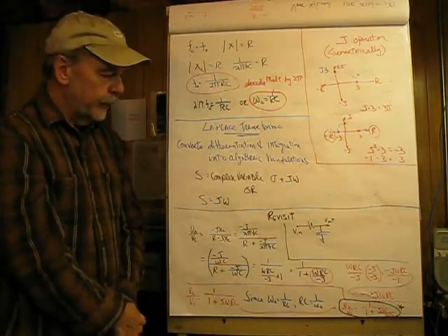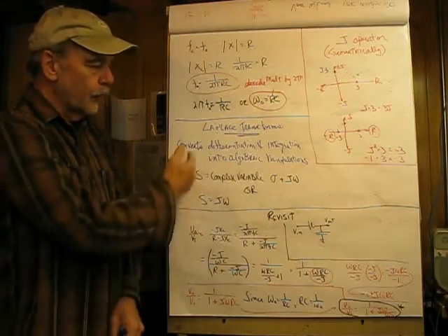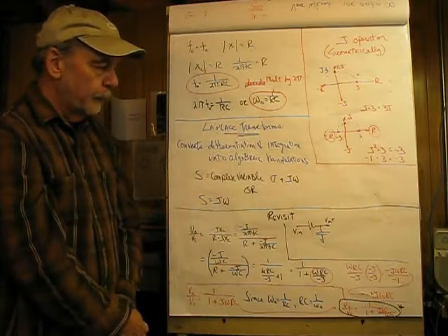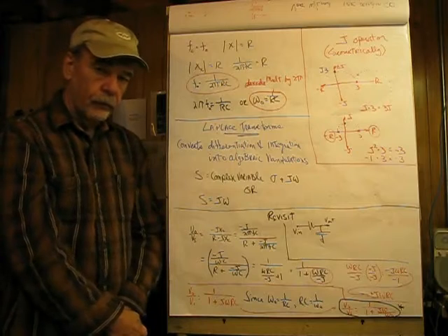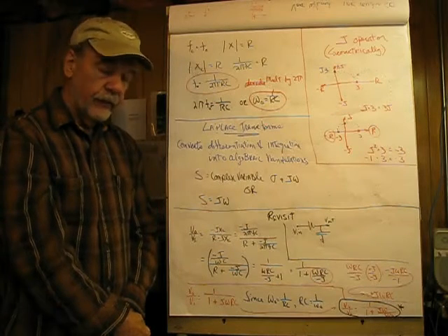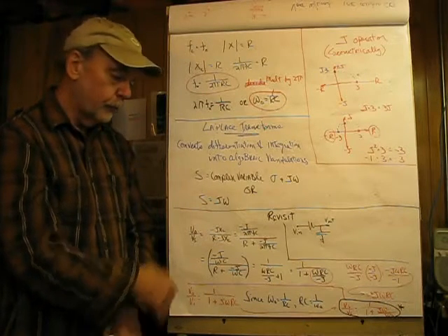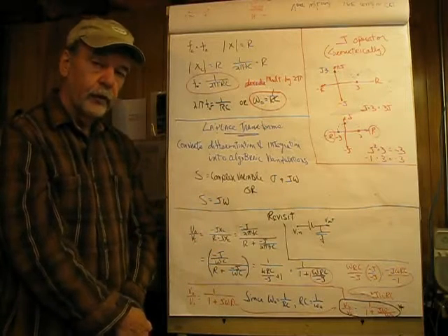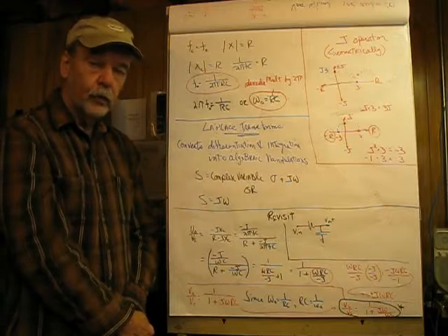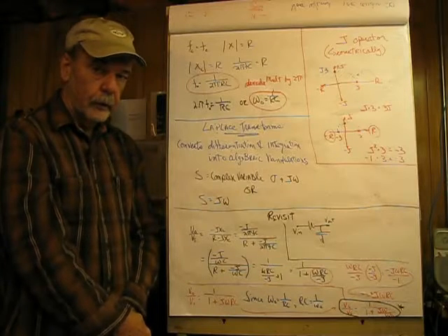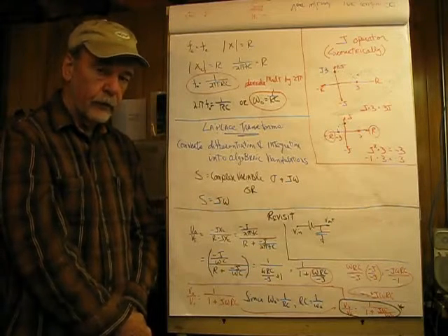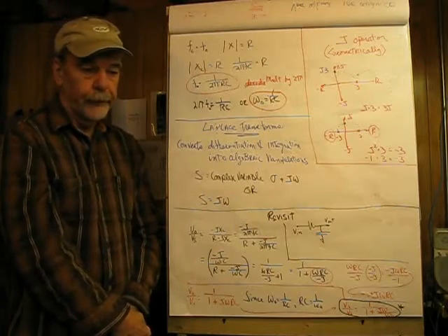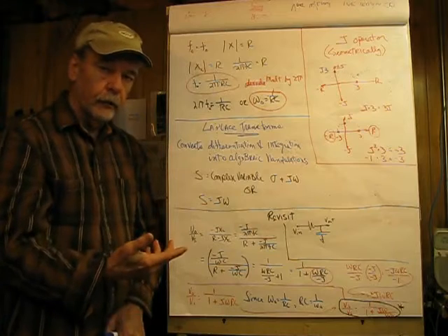Now, we're going to get into a very light introduction to Laplace transforms, and this becomes very useful later. And you're familiar with transforms. For example, using FFT on a scope, you transform from the time domain into the frequency domain, and you can see the frequency components that make up, say, a square wave very easily, that you could absolutely not see in the time domain. Likewise, we transform from the linear domain into the log domain.